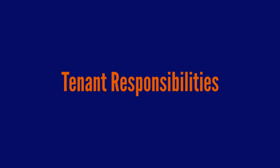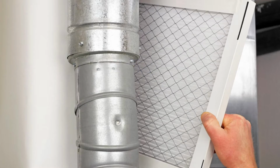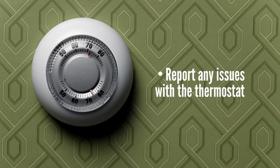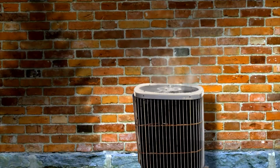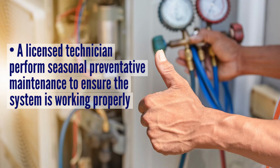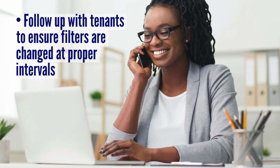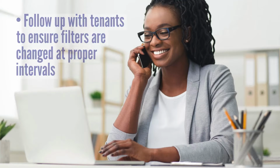The tenant's responsibilities for HVAC maintenance include simple tasks. Tenants must check the filter monthly and replace or clean as needed. They should report any issues with the thermostat. In addition, they must contact the owner or property manager immediately if the system breaks down. As far as landlord responsibilities go, owners need to have a licensed technician perform seasonal preventative maintenance to ensure the system continues working properly. From there, they must educate tenants on how to change the HVAC filter and follow up with tenants to ensure filters are changed at the proper intervals.